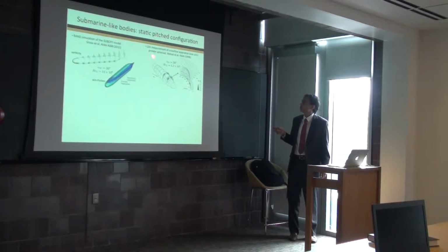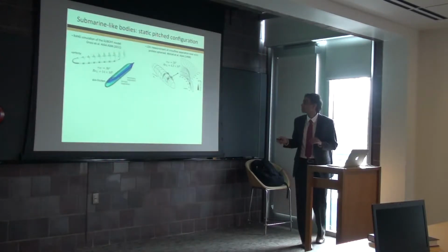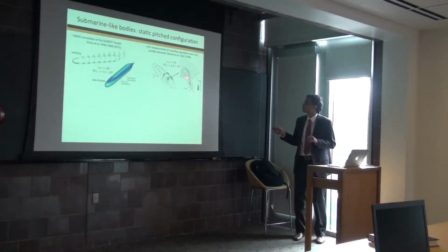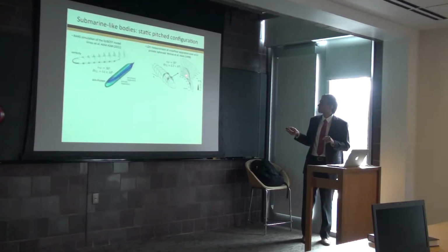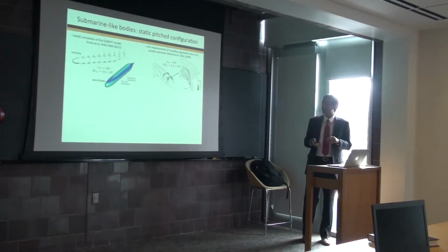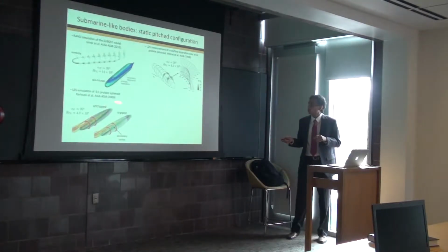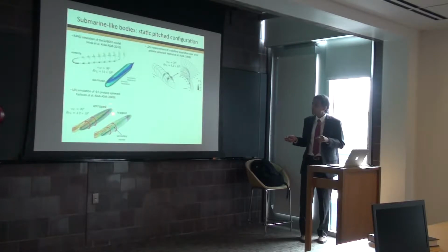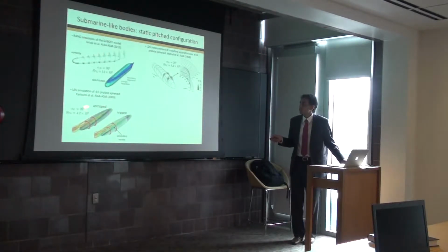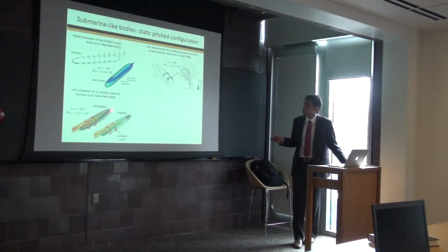This was captured using very detailed laser Doppler velocimetry measurements taken by Wetzel et al., where you can see the footprint of the primary vortex and also a tiny secondary vortex. Why is that secondary vortex important? It influences greatly the trajectory of the first, and therefore you miss the flow physics if you don't simulate the secondary flow. Now, Carlson et al. did simulations of this experiment, and they managed to show this difference very clearly. So here in their simulations, they show that for the untripped case, you don't see the footprint of that secondary vortex, whereas you do for the tripped case.